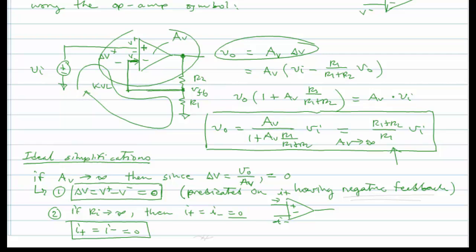It's not that the input terminals of the op amp are actually holding their potential to a 0-volt differential. They actually are high impedance. You look into them, there's infinite resistance. They accept or demand no current, and so they have no ability to actually affect the voltage that is applied to them.